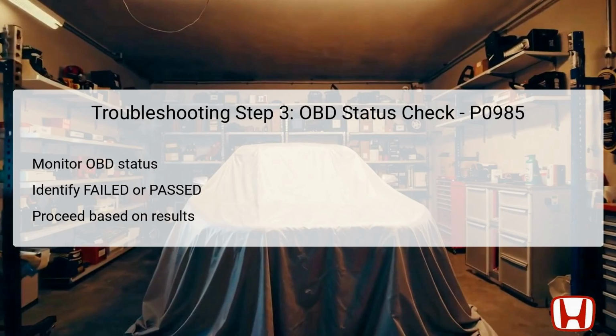The next step involves inspecting for poor connections or loose terminals in the wiring between Shift Solenoid Valve E and PCM. Must be checked thoroughly. If the HDS indicates passed, it means the failure might be intermittent, and you should proceed to check for an intermittent short to ground in the wiring. Should the HDS indicate not completed, retest the vehicle following an appropriate drive cycle for more accurate diagnostics.